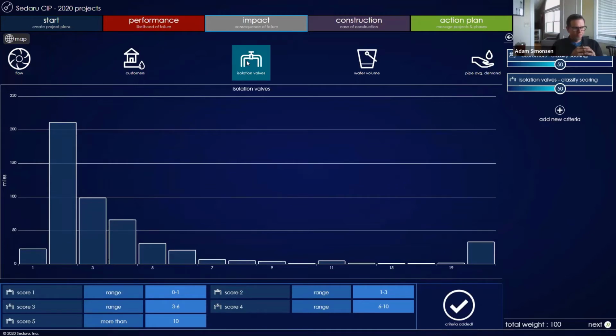Sure. So this one specifically, we're able to take that water network, and we can do it with sewer too with similar attributes. What it's doing is an outage analysis. It's figuring out which valves need to be operated and how many customers will be impacted if that's out of service. So it's more of a pipe criticality perspective. These are things that get brought in naturally with that GIS water network database. Yep, absolutely.